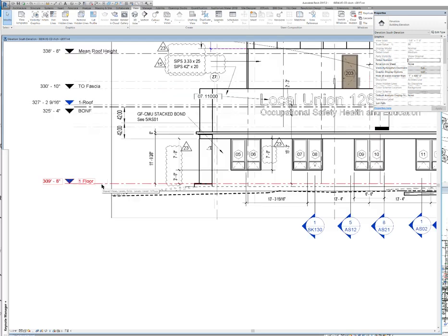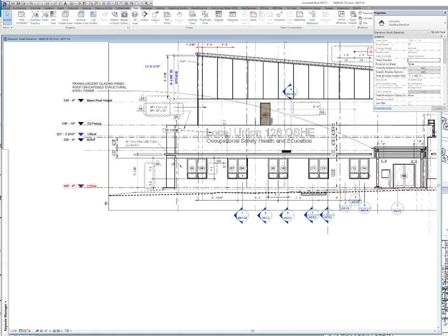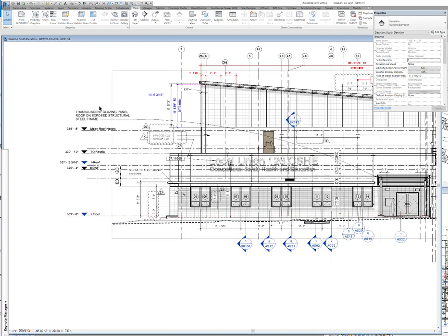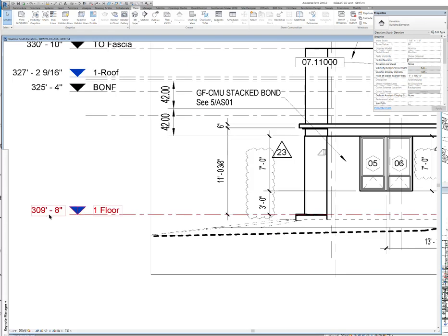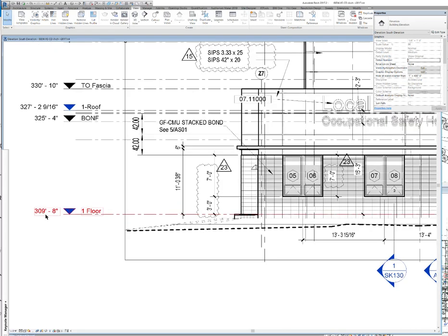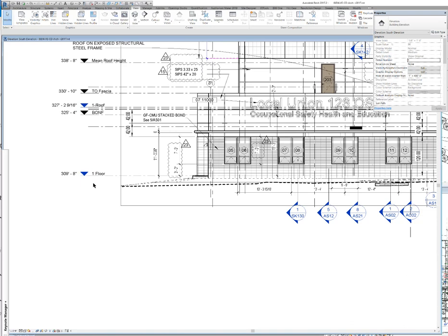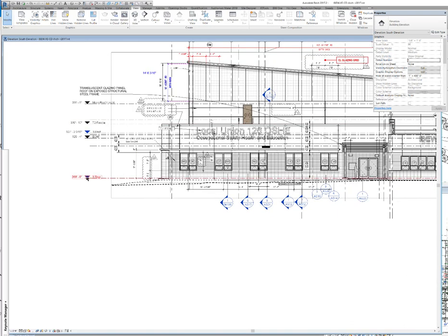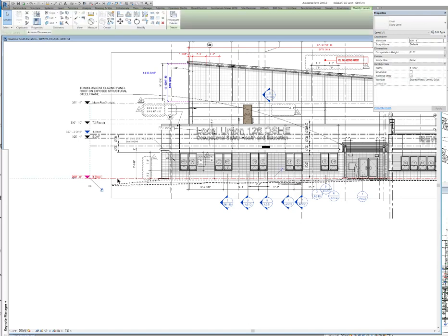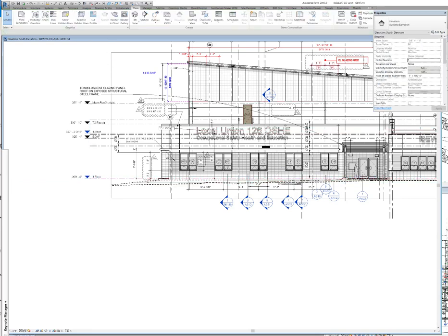available to you. So I've created an elevation for a first floor, and everything's relative off of that in my case. That is set at 309 foot 8 based on a surveyor's plan and the appropriate design. But what you need to have is an elevation that's actually at 0, not at 309-8. So you take this, if this is where you started with a first floor, and that's how the template comes in, first floor, second floor, basement, whatever, level 1, level 2, you need to take this elevation and copy it, Control-C, down 309 feet, in my case, 309 feet 8 inches.